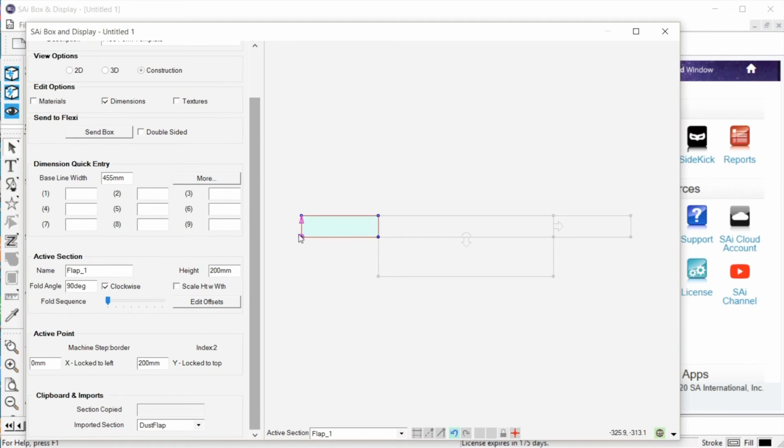So that tells you where your point is in coordinates, and so I want to go 220 this direction on the width. So I'm going to go to this point here and simply change it from 55 to 220, and now I've got my slope side there.